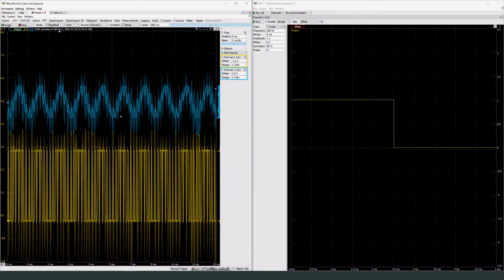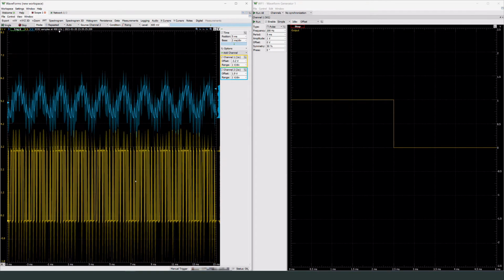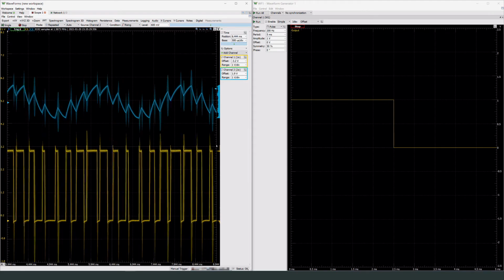It's definitely got some sine wave characteristics here, but what I think is interesting, and just so you know, this is what our input signal looks like. So we have this pulse width modulated signal to help us generate this, which you can see is when it goes on, it charges up. When it goes off, it discharges: charge, discharge, charge, discharge. So that's kind of how you can make that.